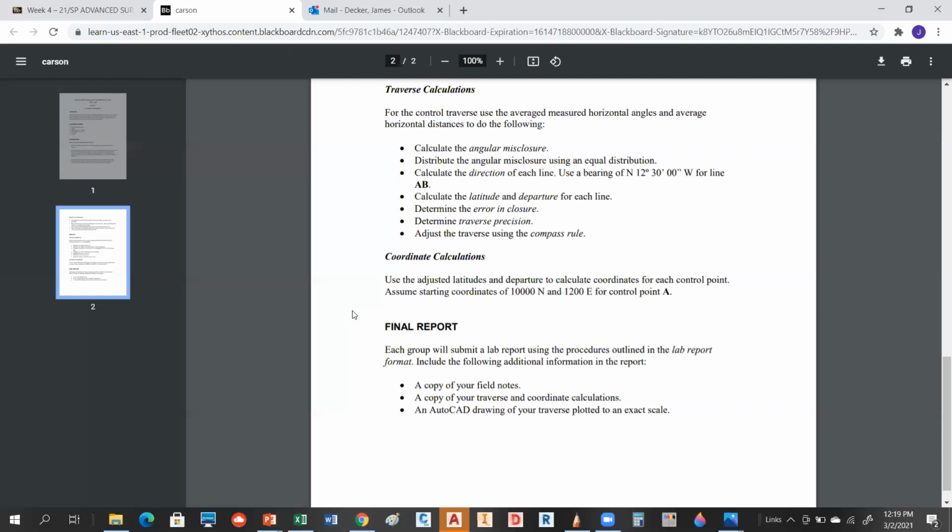We didn't sight on our points the same way each time. Okay. Sometimes we sighted right on the block. Sometimes we sighted on the plumb bob. Okay. Well, that plumb bob would have nothing to do with distance. So the plumb bob would have been related to what? That would have been for our angles. Yeah, exactly. So you hit right there one potential error pitfall: your angles were bad, right? So that's something you could talk about.